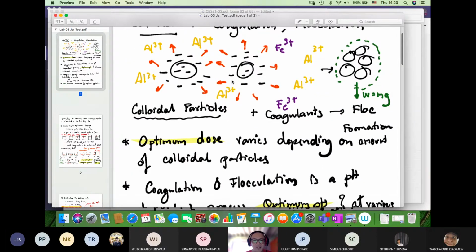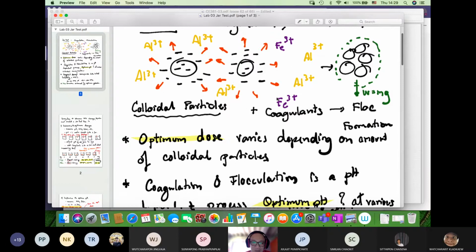I have already mentioned the characteristic of the colloidal particles, which are surrounded by negative charge, and we want to neutralize this charge. That is why we add alum or ferric. So once alum, ferric or other types of coagulants are added to this water, what will happen?